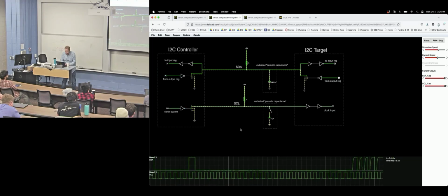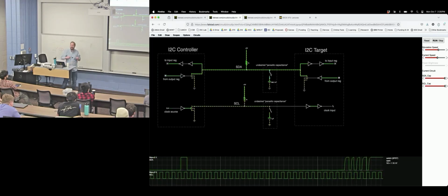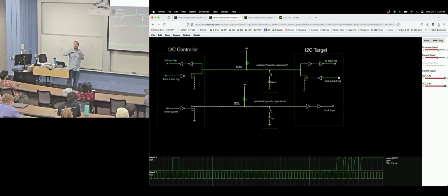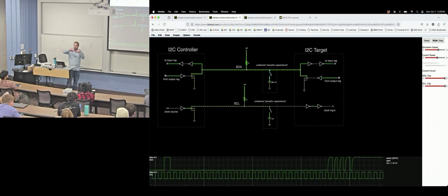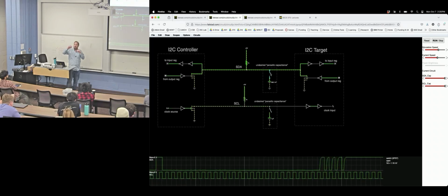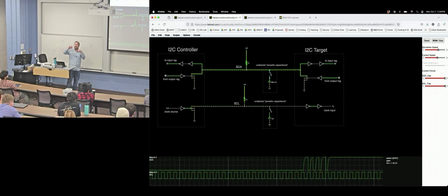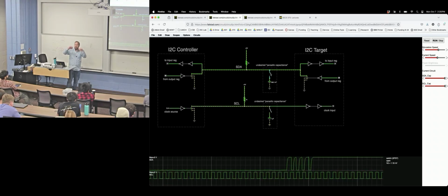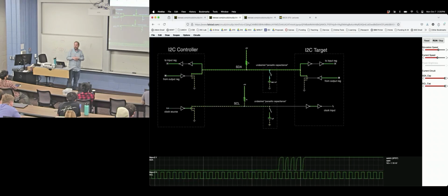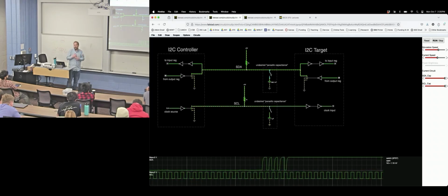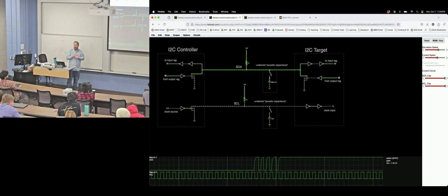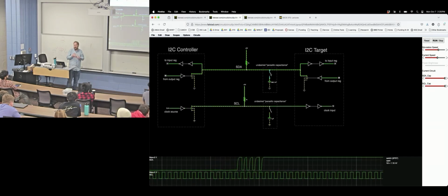In fact, if I take that away, like you saw before, it could be that you're going so fast that your RC charge up time is so slow that you actually miss data points, right? The capacitance is so high that it doesn't reach VDD over 2 to be counted as a logical 1. And in those cases, you either have to reduce your capacitance, probably impossible. You have to decrease your resistor value to drive more current, possible up to an extent, or slow down your bus.